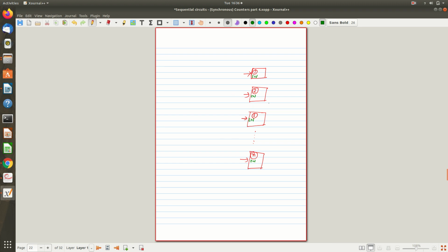So who will enable these enable pins? And that should happen in a systematic way. This is our requirement. For example, if you are executing an instruction, there will be a systematic way: the instruction will be fetched first, so the fetch unit is to be activated, then it is to be decoded, so you will give control to the decoder, and the decoder will work after that fetching. You are not supposed to do the decoding before fetching, that is meaningless, right? Then execution and write back, like that. Okay, so that is the flow.